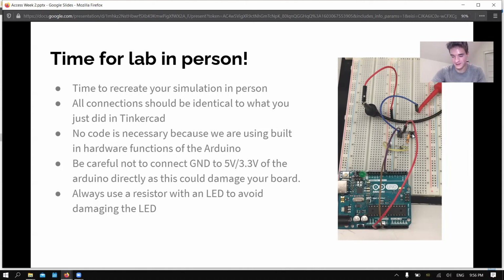Okay, so then I'm going to take the resistor and connect one side of it to the bottom left terminal of the push button, and then the other to just the right terminal of the LED, which is the longer one, if you remember. So it's a little tricky to do that. I use pliers. It makes it way easier. That's a good recommendation. I would do that.